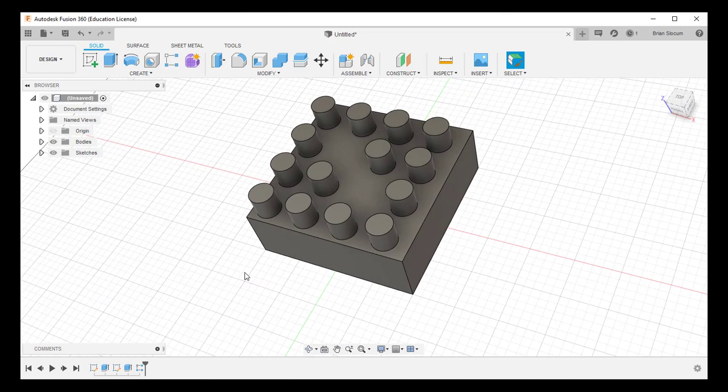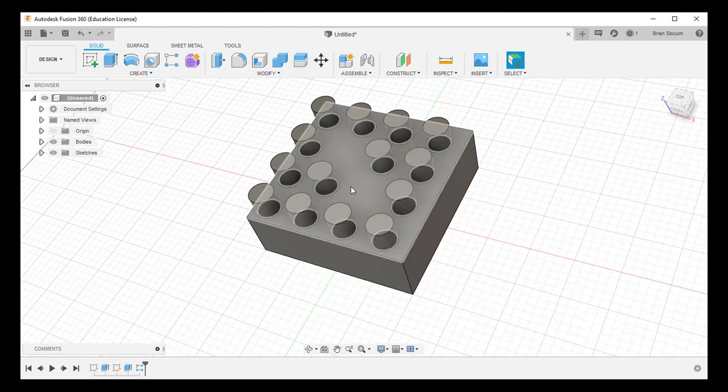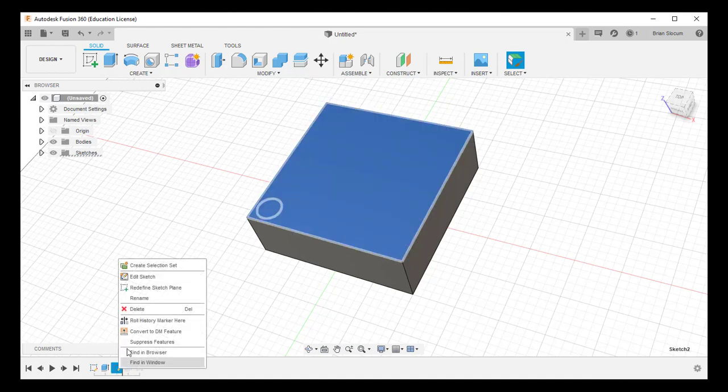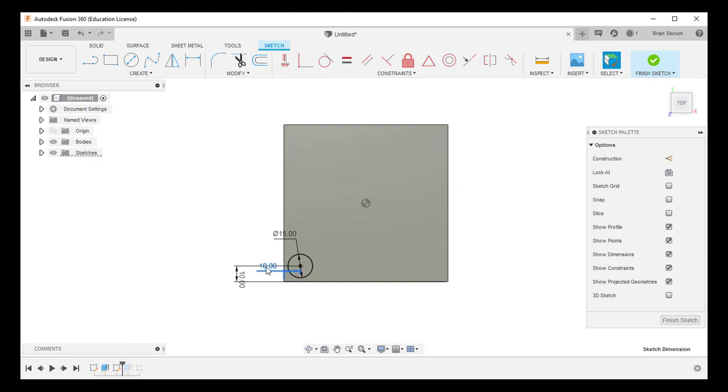And now the last one I'm going to do is a circular pattern or a polar pattern, doing this same process. So I'm actually going to just rewind here. Let's rewind my timeline. Yeah, let's go back here and edit this sketch. And the one thing about this that's a little bit different, I'm going to select you, and I'll select you, and I'm going to make you horizontal to one another. And let's give you a dimension here, just between the edge. Let's give it 50. Just bring it away from the edge.